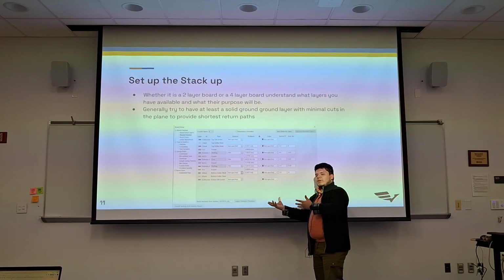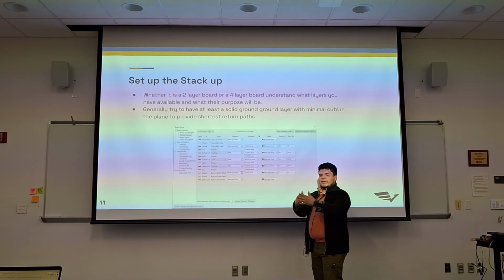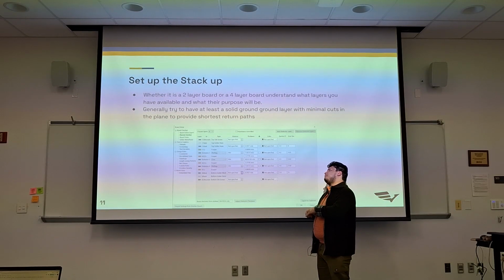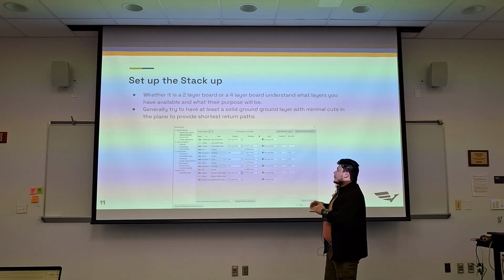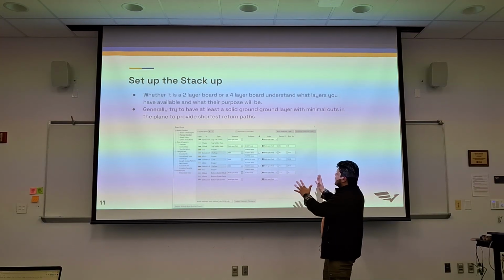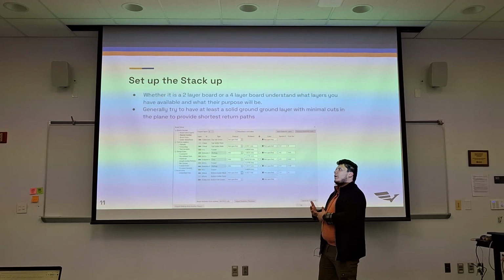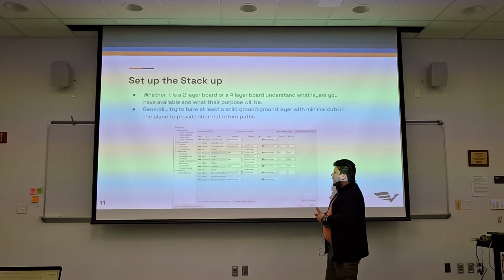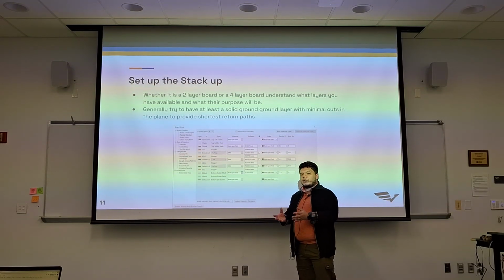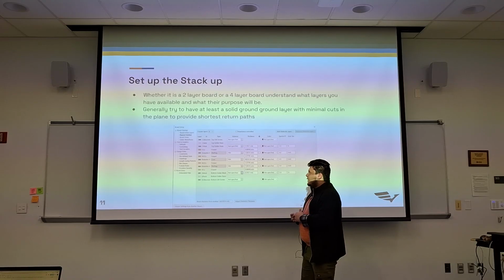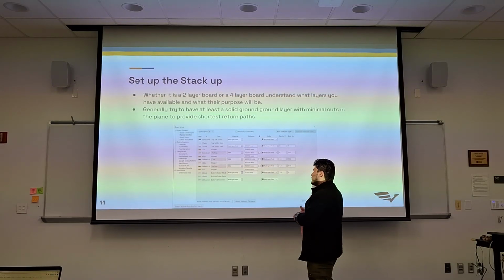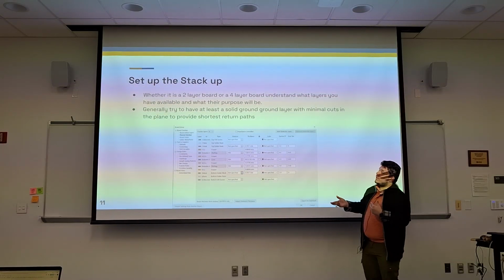You don't have to go and find some other calculator and then compare with your manufacturer or whatnot. Sometimes it's built in. And so going forward, if you do get into board design later on in your career, try to have your stack up as accurately as possible from the get-go, because that's going to save you a lot of time in trying to find those impedance calculations going forward, right?